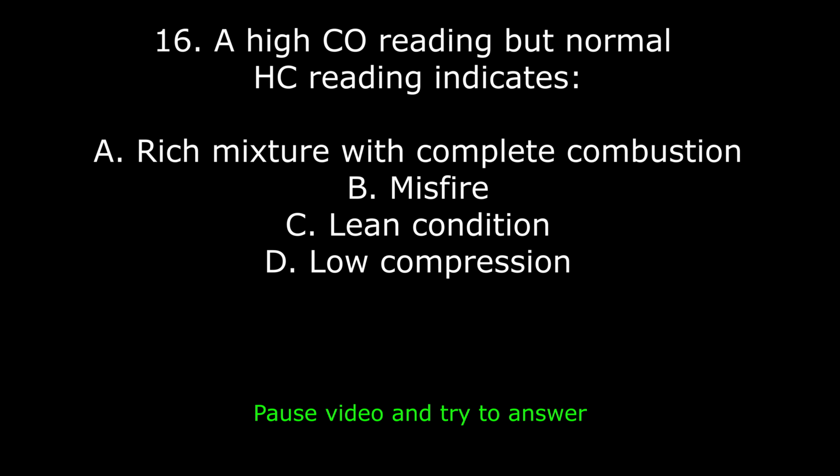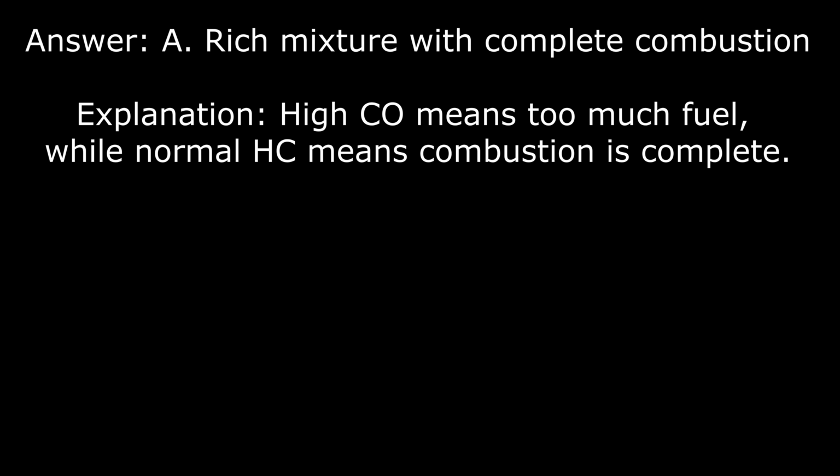16. A high CO reading but normal HC reading indicates A. Rich mixture with complete combustion, B. Misfire, C. Lean condition, D. Low compression. Answer: A. Rich mixture with complete combustion. Explanation: high CO means too much fuel, while normal HC means combustion is complete.